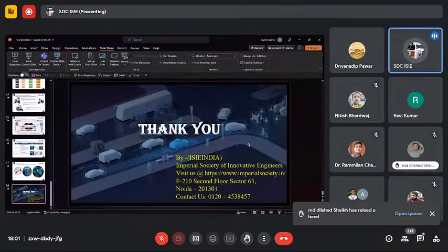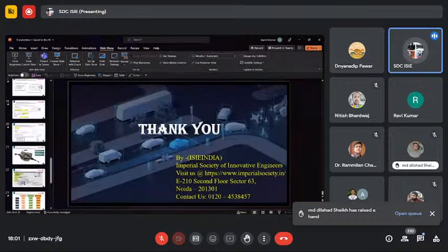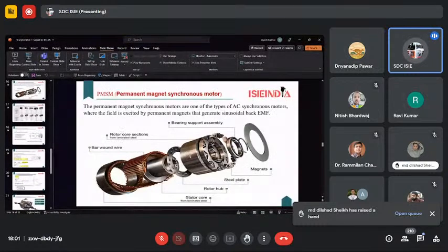So the configuration and the manufacturing part is very much complex as compared to the permanent magnet synchronous motor. In the synchronous motor, at the center rotor, we provide a DC power supply to the field winding to create a rotating magnetic field and interlock. By removing the power supply to the field winding and directly placing a permanent magnet in the synchronous motor, that's why we call that motor a permanent magnet motor.